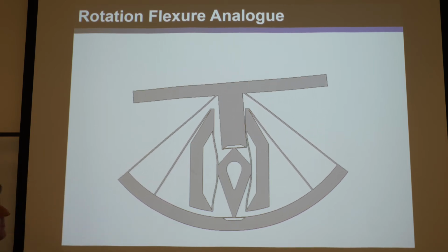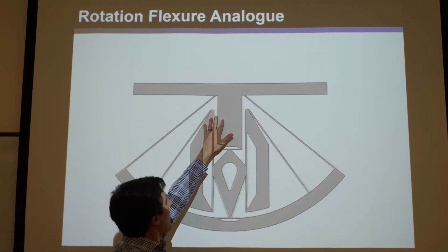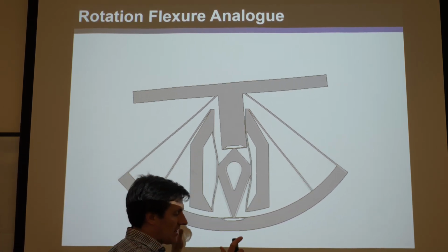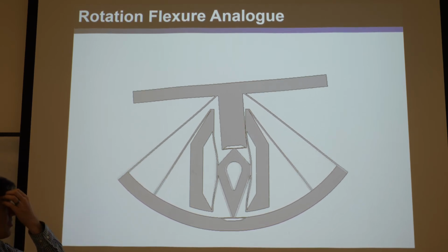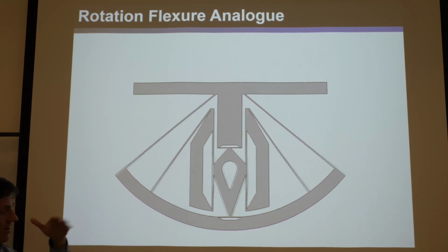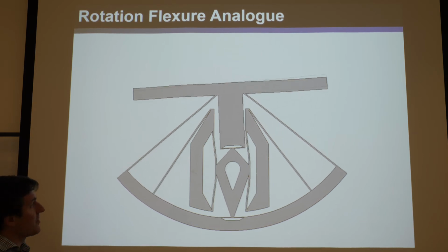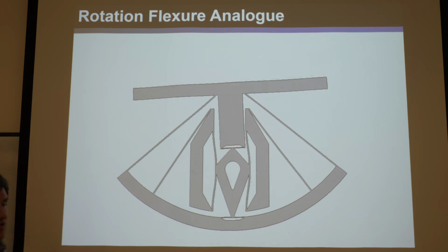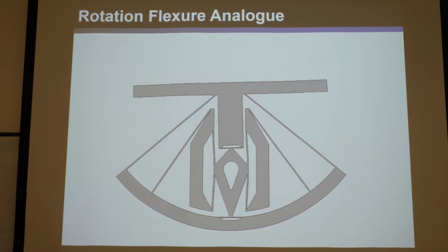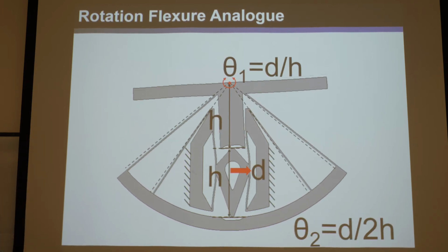Nothing's under constraint. If you hold this fixed with respect to the ground, this and this will be totally locked up, so there'll be no lack of control if you're actuating this. So under constraint is gone, obviously. That's why it's called an under-constraint eliminator. And the cool thing is this is forcing the 2-to-1 ratio, so there's no parasitic errors. Okay? And so check it out.